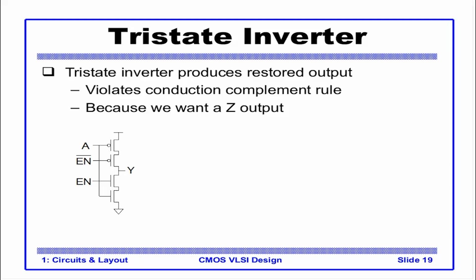This part, what does it represent in isolation? What it represents is that these 2 transistors here, this PMOS and this NMOS, represent an inverter. But the same input is not connected here. NMOS is connected to EN and PMOS is connected to EN bar, just like in the case of a transmission gate buffer. A single input A is connected to PMOS here and NMOS here.